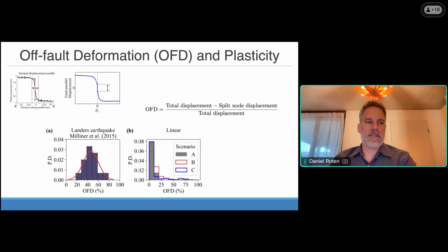We then used this nonlinear code for some important earthquake scenarios. The first one was the ShakeOut scenario I mentioned before. Those maps compare the peak ground velocity in the Los Angeles region, to the left for a linear case and on the right for the nonlinear case. You can see that those velocities are significantly reduced once you account for plasticity. The amount of reduction depends a bit on how you specify those nonlinear parameters in the model, but it can range from 30 to about 70%